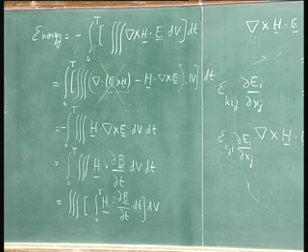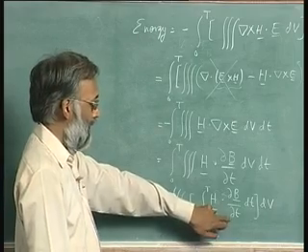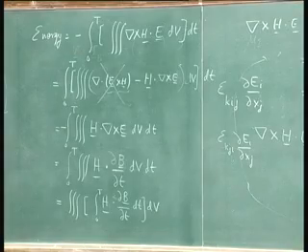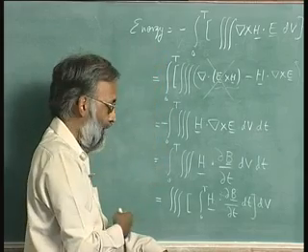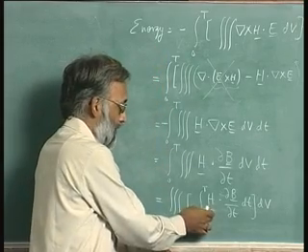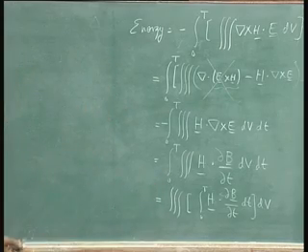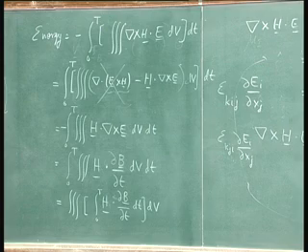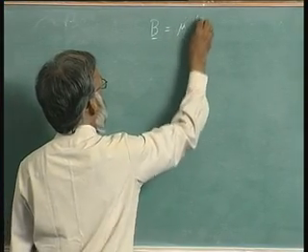If B is not equal to mu h, this is still true, and in fact for magnetic materials this is exactly what we will have to do, because what you will find is that if you cycle in time the magnetic field, make it rise up and make it come back down, that this does not give you 0, because there is some loss within the magnetic material itself. But for now, let us assume that B is equal to mu h.